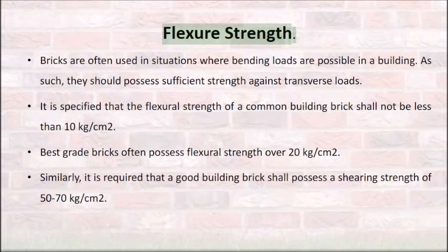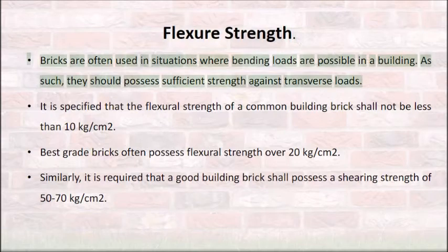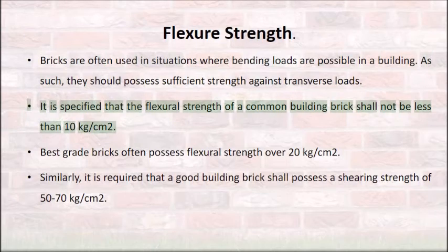Flexure strength. Bricks are often used in situations where bending loads are possible in a building. As such, they should possess sufficient strength against transverse loads. It is specified that the flexural strength of a common building brick shall not be less than 10 kg/cm².